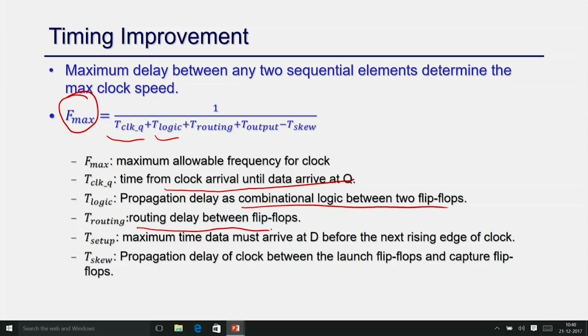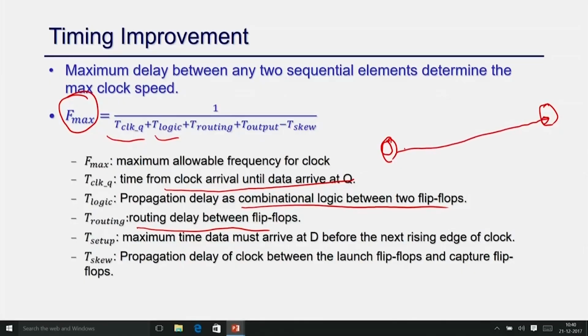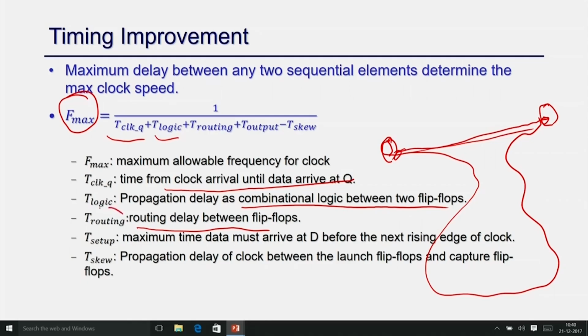When you physically place those two registers, if you have a register here and a register there, they may be placed very close by in the actual IC, or they may be placed very far, right. If they are placed very far, then there is some routing delay as well, because now you have to connect these two pins. The output is going to this input, and it might go directly like this, or it might be routed like this. So, the routing path automatically becomes very long. So, there is some time involved in routing also, and also there is the setup time of the registers.